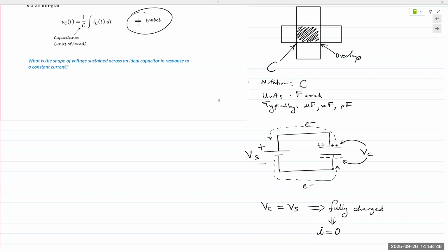All of that energy is released in an instant. So there'll be a spark. But once you have the spark, the capacitor is now drained. Done. So if you have a very, very tiny capacitor and you charge it and you just short its terminals, chances are you won't even see that spark, because most capacitors are very small. But if you take a huge capacitor, like a big cylinder, it has a large amount of energy stored, you short its terminals, you have a big spark.